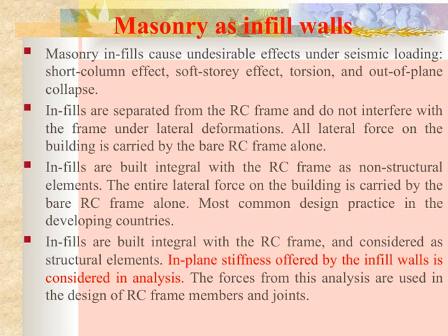On the other hand, there's a different approach where infill walls are built as integral parts of the RC frame, and they're considered structural elements. In this case, their in-plane stiffness is taken into account during analysis, meaning we assess how they contribute to the building's overall lateral resistance. The forces calculated from this analysis influence the design of the RC frame members and joints, leading to a more integrated and potentially more seismic-resilient design.